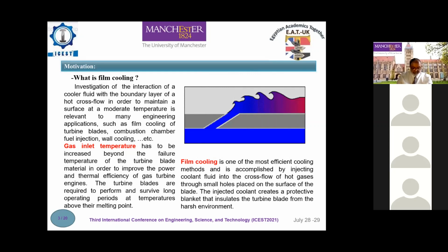With the aid of the film cooling technique, higher turbine inlet temperature is possible, which in turn improves the power and thermal efficiency of the gas turbine engine. Therefore, film cooling is one of the most useful techniques for protecting turbine blades from thermal failure caused by operation in a high temperature environment, and effective film cooling is of critical importance to the gas turbine industry.